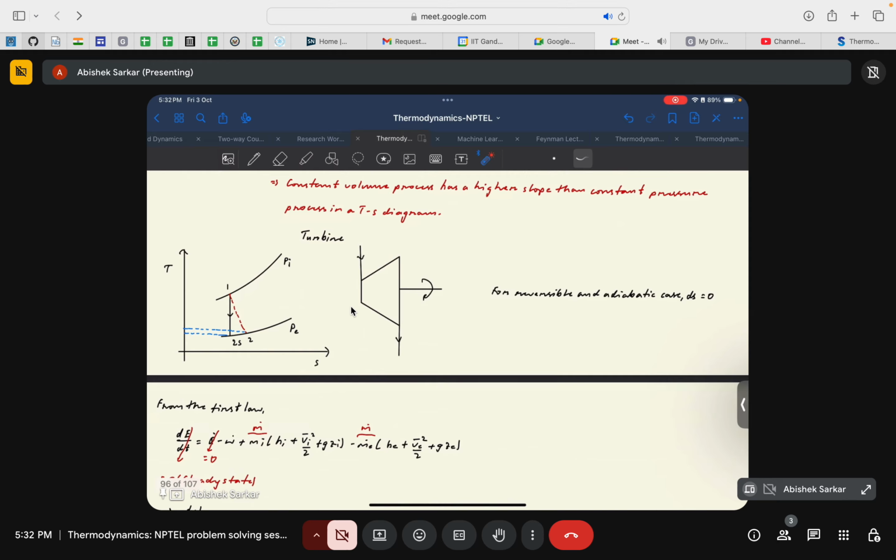In the Rankine cycle it was represented by a straight line. In this TS plot, this vertical line represents an isentropic expansion. As I mentioned in the standard lecture, vertical lines in TS plots represent isentropic processes. So this expansion through a turbine, if done in a reversible manner, represents an isentropic expansion, and that is what we have been considering till now.